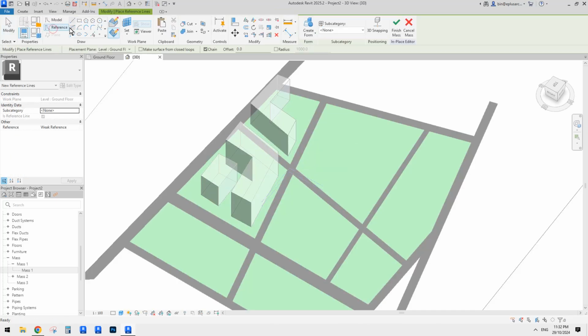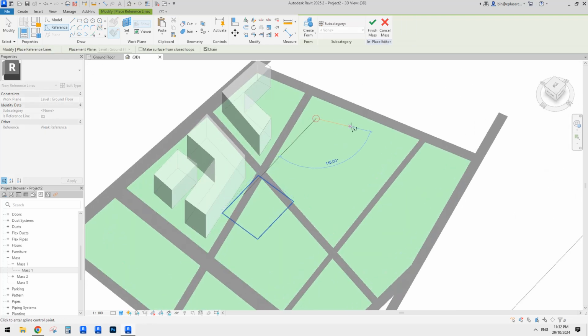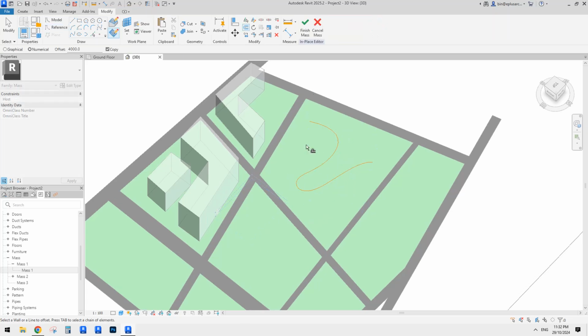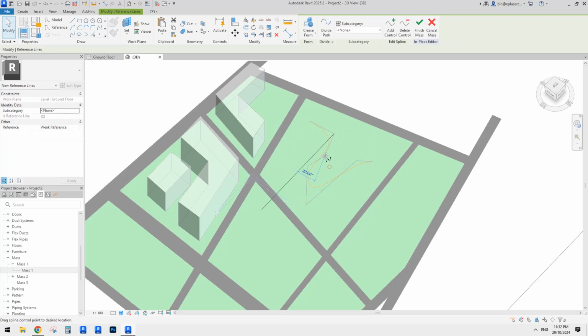You can also try different shapes. For example, you can use spline. Let's just do some interesting shape, and then we can offset maybe 10 meters. I'm not sure, 10 meters. Can we? We can't. Yeah, which means the curvature is just too sharp, right?